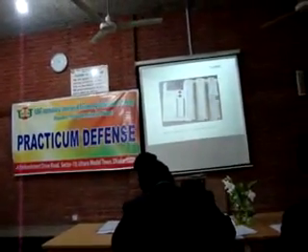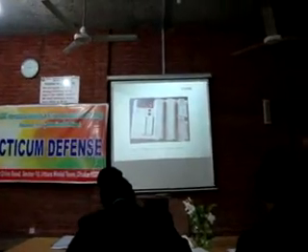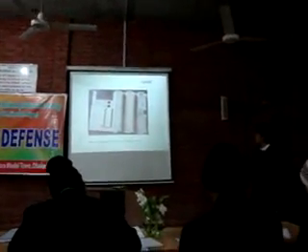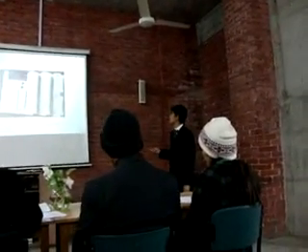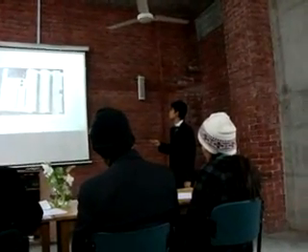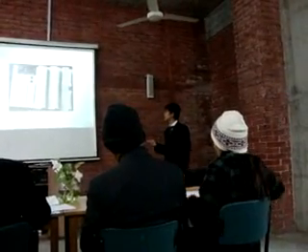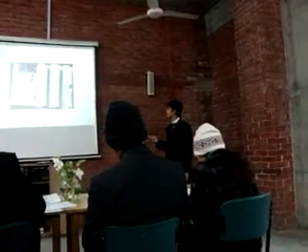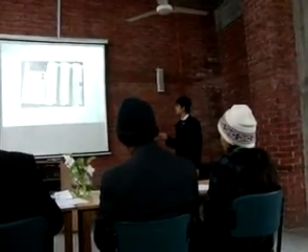If this battery is okay, the battery indicator will show that the battery is okay. If we run the program, the run indicator will show. If the IO devices are connected properly to the modules, there is a signal showing. And if there is an internal processor problem, a CPU problem, then the error indicator will flash, and there are some different levels showing.